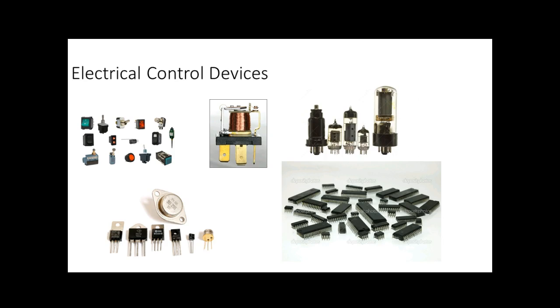Of course, the problem is they've got glass in them. When we drop them, we break them. They pop every once in a while. And to make these things work, they require a pretty high voltage. On the anodes, usually they're running around 200 volts. And they get hot, so they consume energy to work, because to make the cathode work, we have to heat it up with a heater. Okay, y'all understand that? We don't call them solid state, but they had no moving parts.